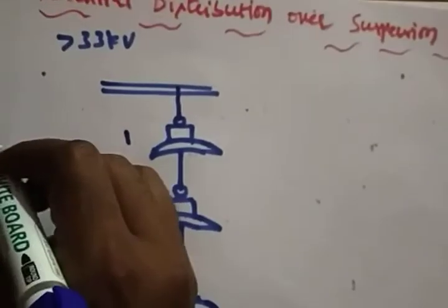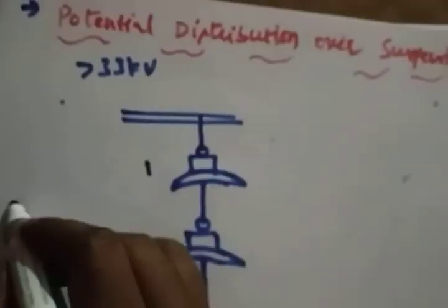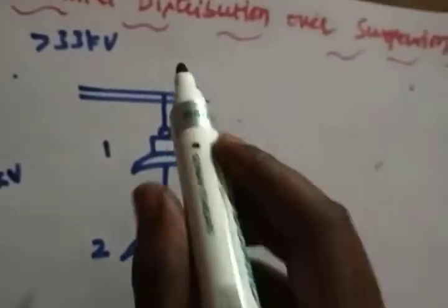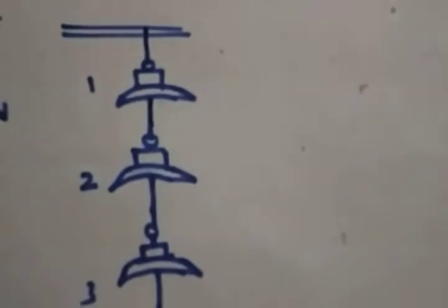So it can be used for 33 kV. So from seeing it itself, you can know how much current the conductor carries. You can easily say there are 3 discs, so there might be a 33 kV line passing through this. Right? This is a metal conductor, and this is a metal conductor, and this is a dielectric medium. So we can expect a capacitance to exist now. I hope it's clear.